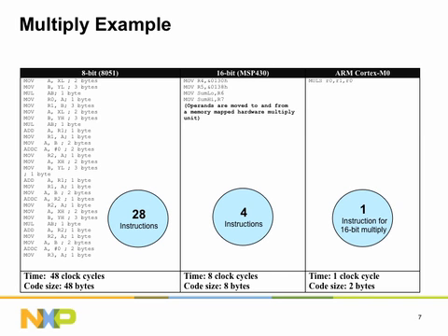Code size can also be affected by the width of the data the processor has to deal with. Let's consider an example where an 8, 16, or 32-bit microprocessor is receiving data from an integrated 10 or 12-bit analog-to-digital converter. To support basic filtering of the 10 or 12-bit ADC data, a microcontroller typically uses a 16-bit multiply.